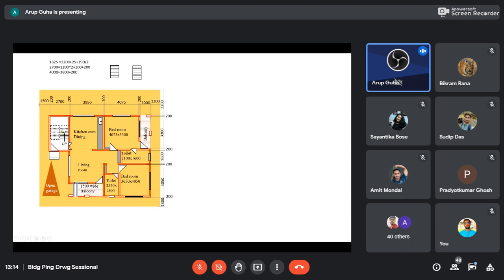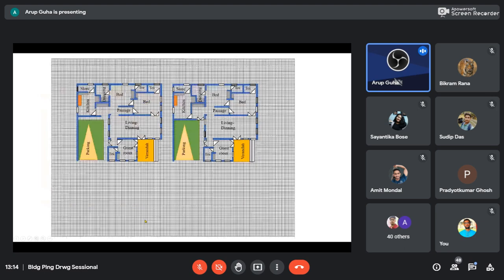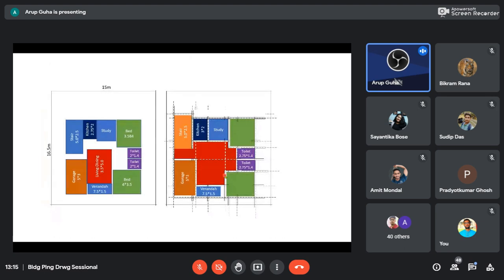So then what has happened is that the stair has been cut at this level. This portion we have removed. So these lines we are seeing in full line, the remaining things we are not seeing. So to suggest that, we will put a dotted line here. That is why in the earlier picture we inserted dotted lines to show the beams.